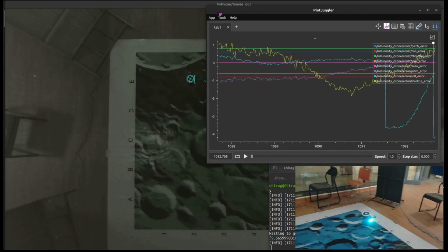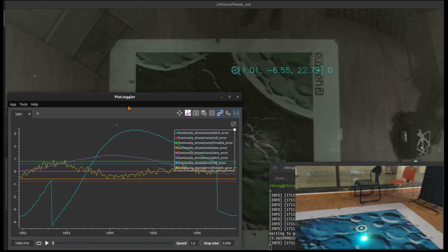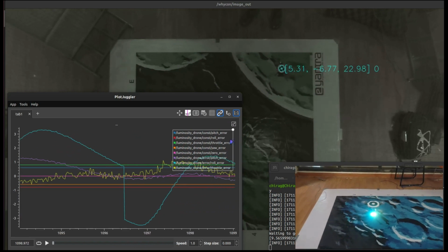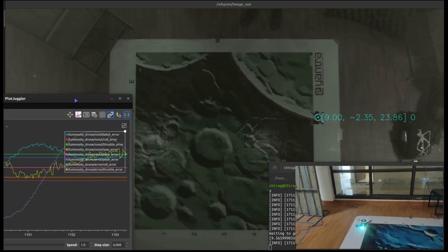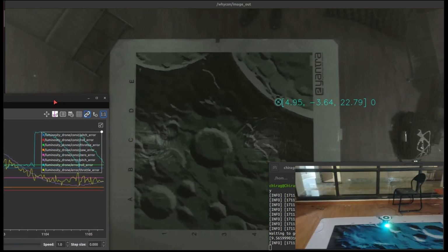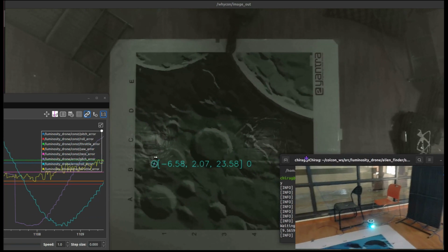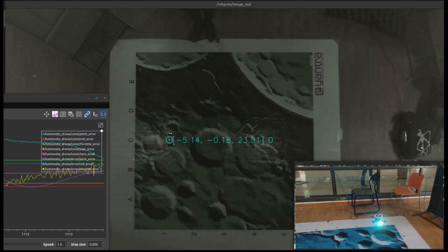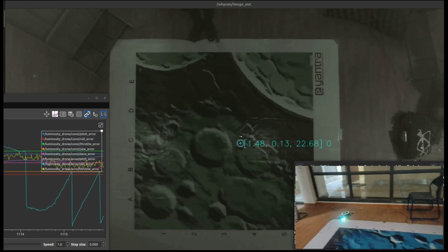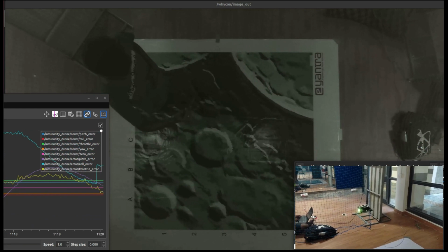In our case, we are not controlling the yaw of the drone. It is controlled by the flight controller using its IMUs. You can also see some constant lines here. These lines represent constant errors of 0, plus minus 6 cm, and plus minus 8 cm for understanding how our drone performs. So as you can see, our drone is performing pretty well in its search algorithm. With even more rigorous PID tuning, our drone can achieve even better performance.